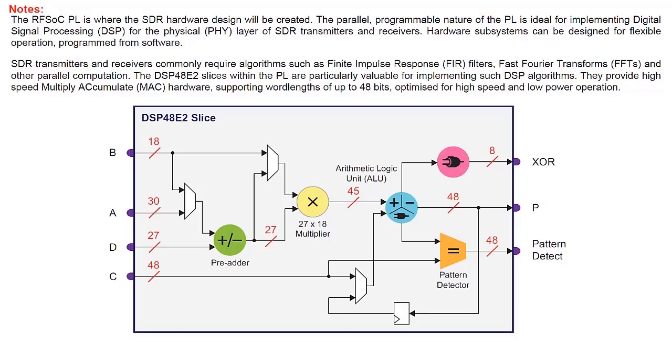So lots of resource and capability for designing our software-defined radio systems. And there's a quick look at one of the DSP48 slices. On the slice, we have tremendous DSP functionality with a multiplier, and we've got pre-adders, post-adders, and so on. And you've got many thousands of these that you can configure on your single RFSoC device.